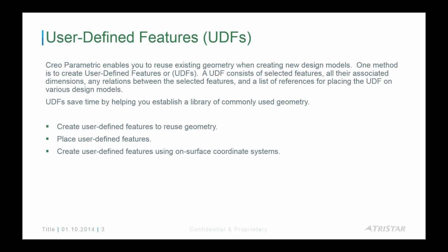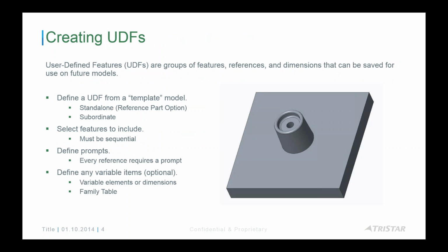UDFs will save us time by helping us to establish a library of commonly used geometry. So in this section, we're going to discuss how to create user-defined features to reuse geometry, how to place those user-defined features, and then also creating user-defined features using what's called an on-surface coordinate system.